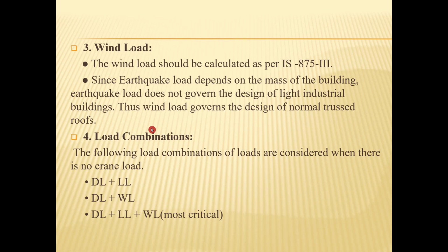We have to consider the load combinations: dead load plus live load, dead load plus wind load, and dead load plus live load plus wind load, which will be the third one, the most critical one for the analysis.